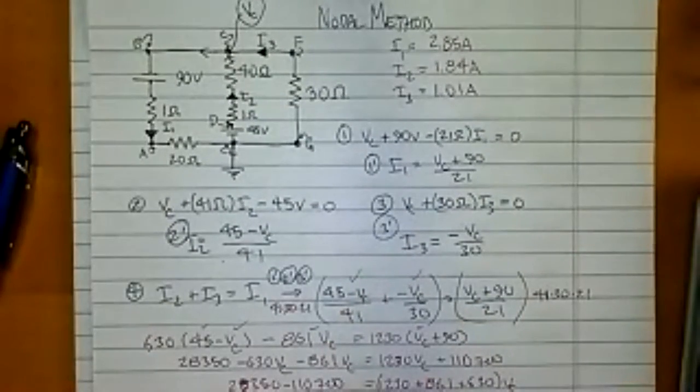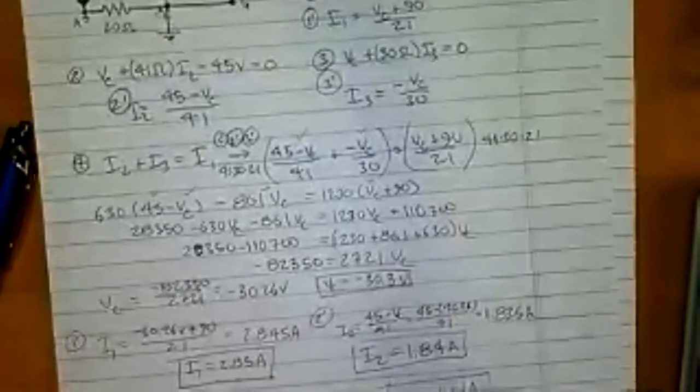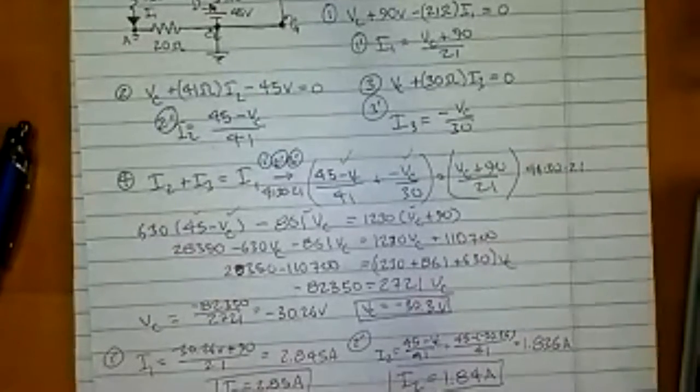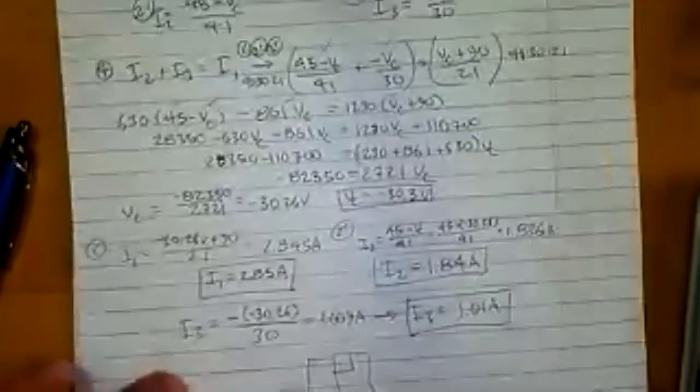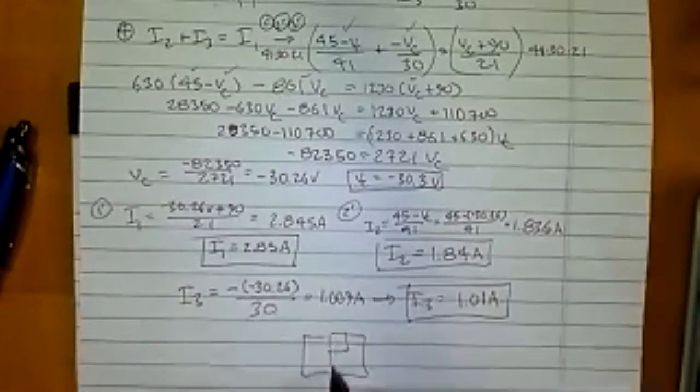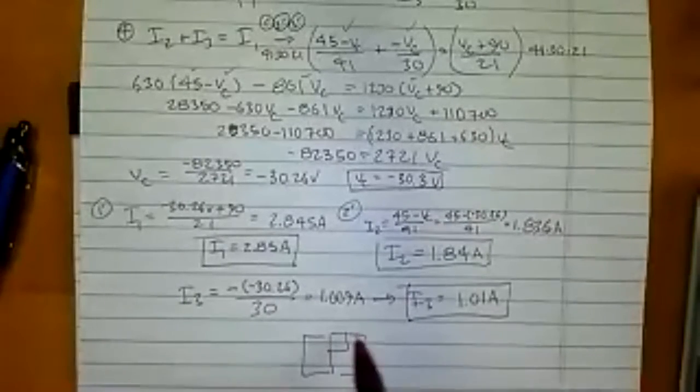So that's the nodal method. It works really wonderful, especially when you have circuits where you've got distinct nodes that don't break up into other nodes or don't have other nodes connected to it. It gets ugly if you have circuits like the one we had before. So there'd be resistors and batteries on here, resistors and batteries on here, and resistors and batteries on here.